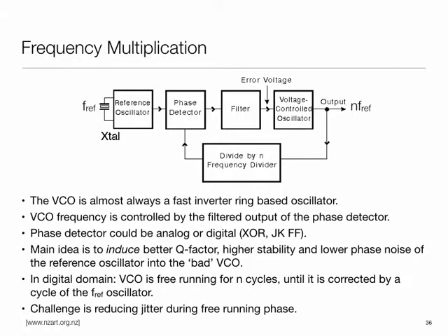Usually these PLLs are programmable, so you can program these n's, or if it's a fractional one, then both the factors, and then generate a lot of different clocks. So what you would typically see is some sort of a clock control register whereby you can control the actual clock on which your processor core is operating, and all of that is happening because you're essentially reprogramming the PLLs. And then there would be PLLs generating fixed signals specifically for USB and things like that.